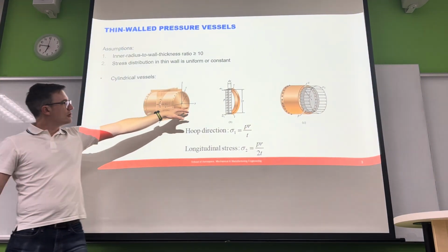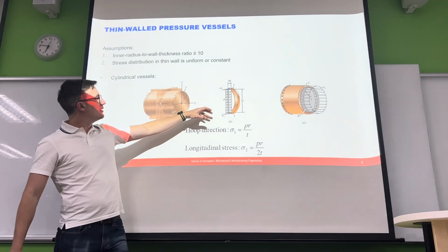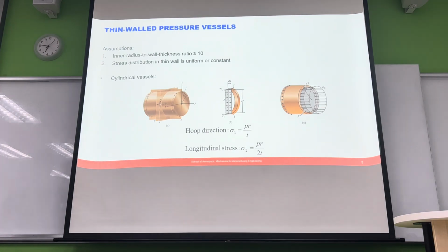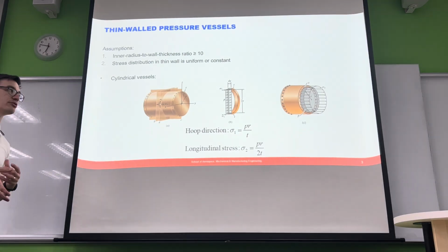So we internally pressurize it, and again, the key thing to remember with all these systems is they need to be in static equilibrium, no matter which way you cut it. So if we cut it this way, that way, and we analyse the external loads being placed on the system, and we cut through a surface, the internal stresses have to balance each other out. So the sum of forces and the sum of moments always have to balance each other out.